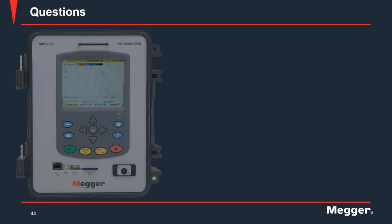Now, one of the key things you may also end up getting into is what's called supra harmonics. These are harmonics that go up to about 150 kilohertz. And really, right now there are no standards on them. They're really in their infancy, and they're even discussing the proper methodologies of how to record them. Because even with this type of thing, you can get induced signals in the line at those frequencies. So there is still a lot of work to be done in this range, but again, the limiting factor is the CTs and PTs and the equipment.